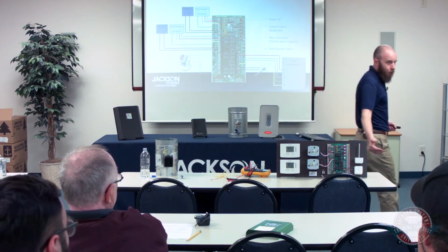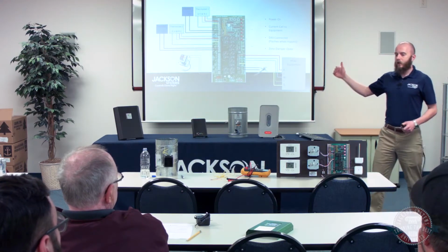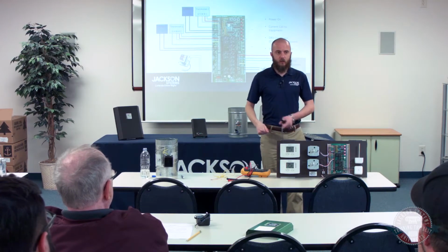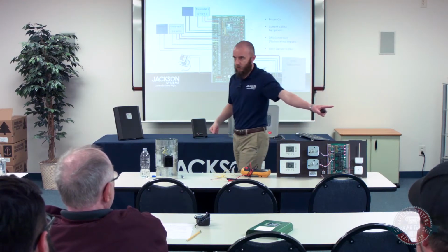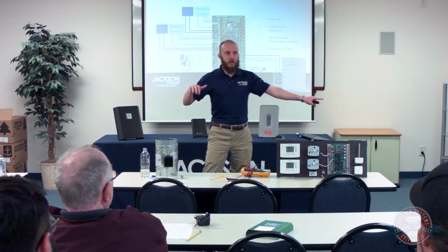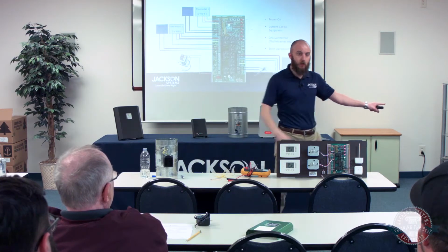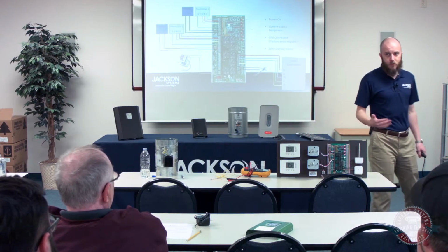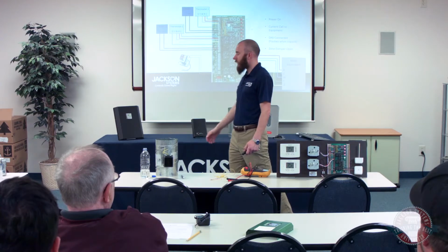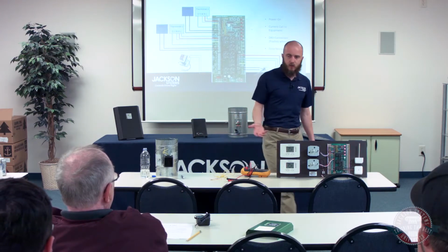So when a zone calls, the board sees that call, says, okay, we're going to send that call through. It'll pass that call through to the equipment, open the calling zone's dampers or leave them open, and the non-calling dampers, it'll power closed. All right, so only the zone that's calling is going to get the conditioned air, the heated or cooled air, whatever it is. That's your basic sequence of operation.